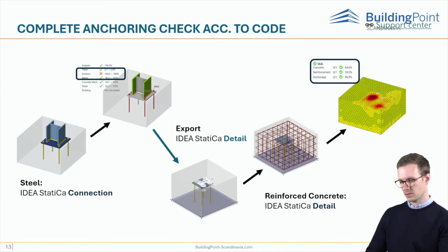And these are the steps. So you can start in the IDEA StatiCa connection application and analyze the anchoring. And you will find the failure due to them being too close to the edge. You can then export to the detail application, and the anchors and the base plate and all of the load effects are exported. When you're in the detail application, you can define the reinforcement. And the last step is to calculate and receive the results that consider the reinforcement in the concrete, giving you a complete check of the anchoring.